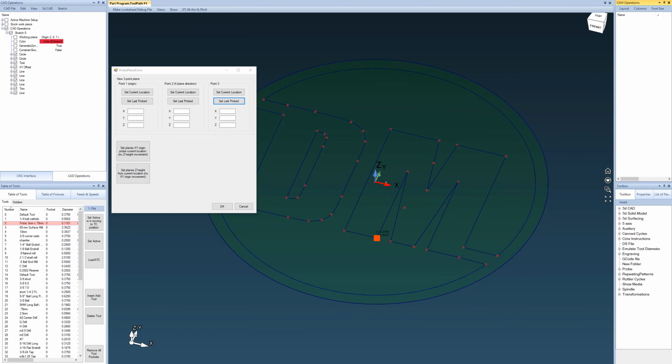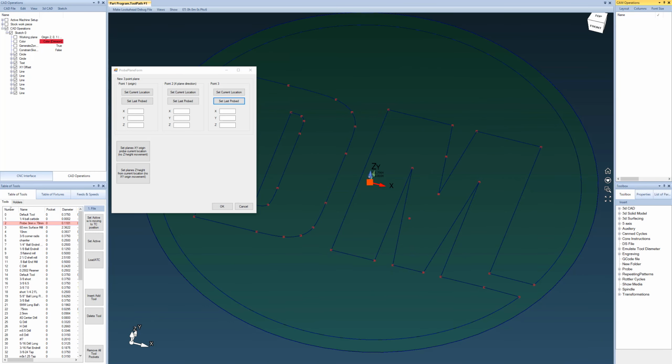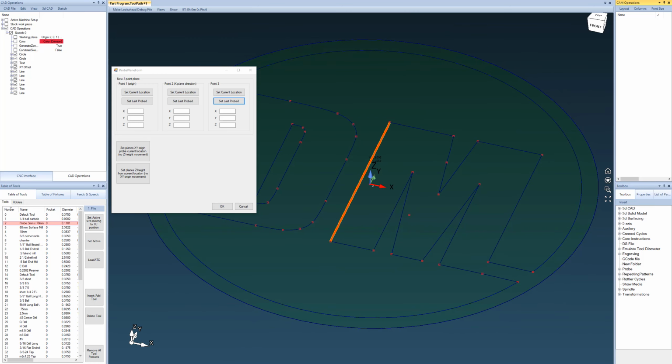If you rotate this plane 180 degrees around the z-axis of that plane, your x is going to go in the negative direction, and your y is going to go in the negative direction. So you can orient a 2D sketch on that plane in any orientation around the z-axis, and position it anywhere on that plane using the origin. That's a really important concept to understand here.